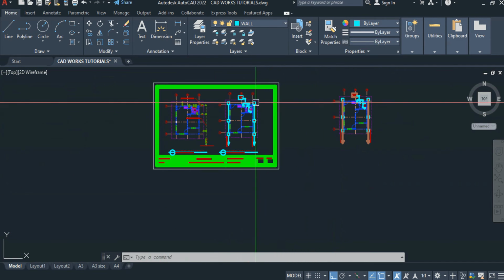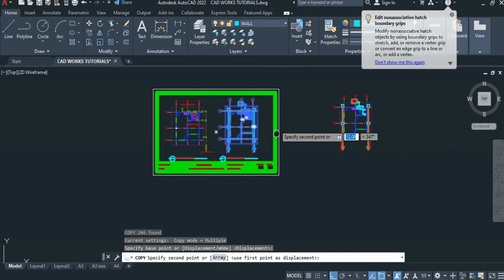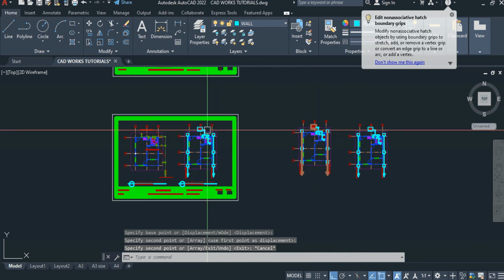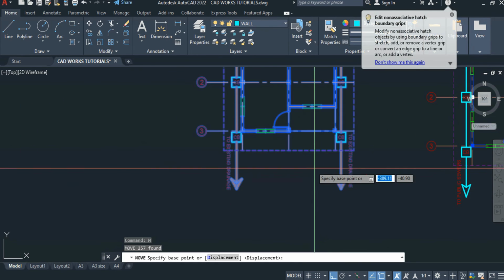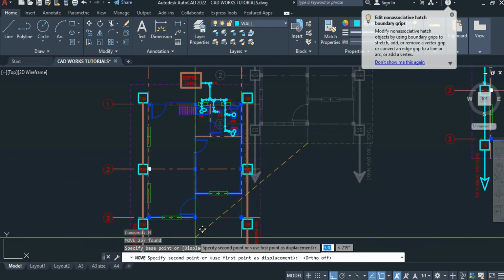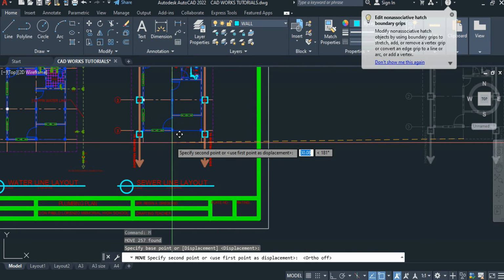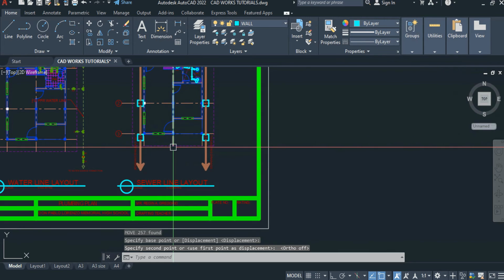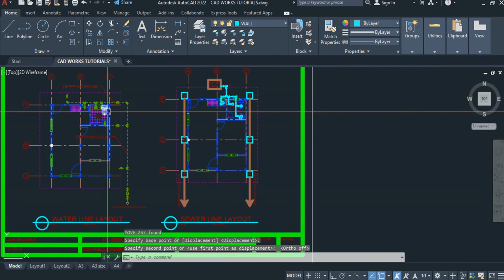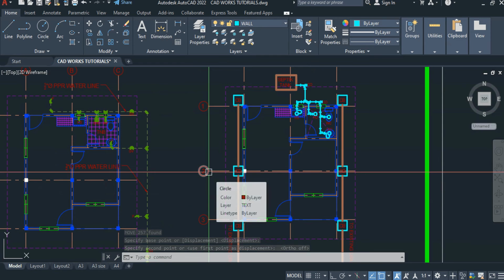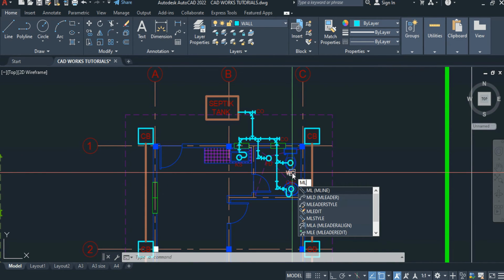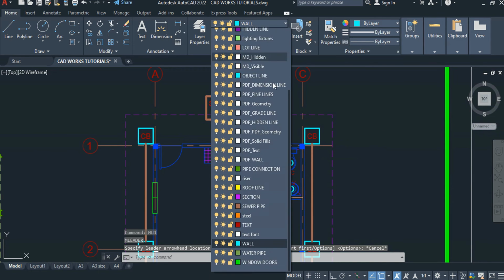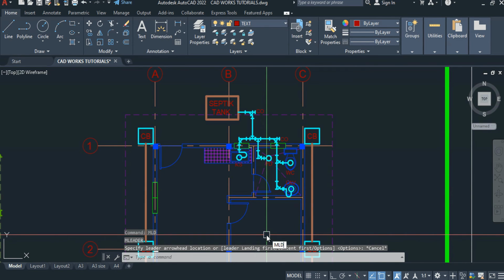Okay, so before that, I'm going to move this drawing. I'm sorry, erase. Let's try to move this drawing dito. Okay, F8, somewhere here. Okay, then let's try to label yung drawing natin by using MLD. Okay, so try here. Let's try MLD, enter. Let's change the text first. Okay, MLD, click,